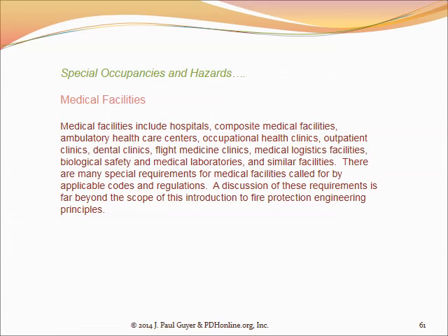Medical facilities also, because the population includes patients who are not mobile, rely in many cases on the concept of an area of refuge. And this would be like an elevator lobby on a given floor. The elevator lobby would be shut off from the corridors and the rest of the spaces with automatic closing doors that would close automatically in the event of a fire.